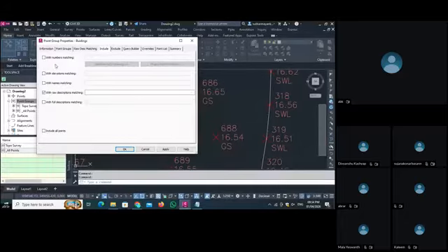We can select your points with the help of number matching, elevation matching, name matching, or raw description matching. So we use this raw description here. For the building, we have the raw description as BLD in our point file, and we have to put a star here to collect all the same points, and then we apply with the OK button.